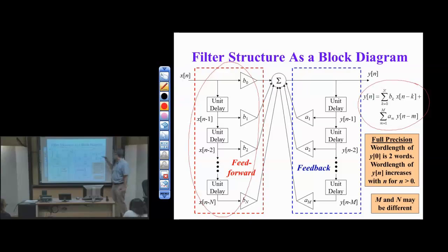So that's the left hand. The first term corresponds to the feed-forward section, the FIR section. The second term corresponds to the feedback section. The second term is a tap delay line, remembering the previous output values. Same structure, same code can be used for both. Makes it really easy to implement, very fast to implement, whether it's in MATLAB or C or assembly or whatever.